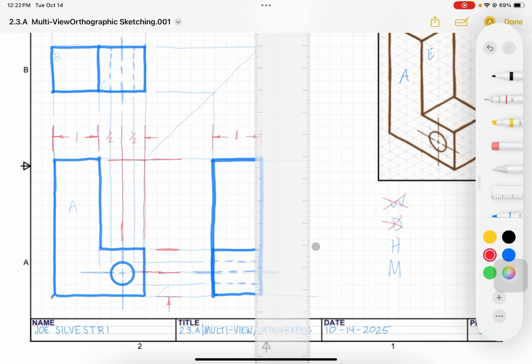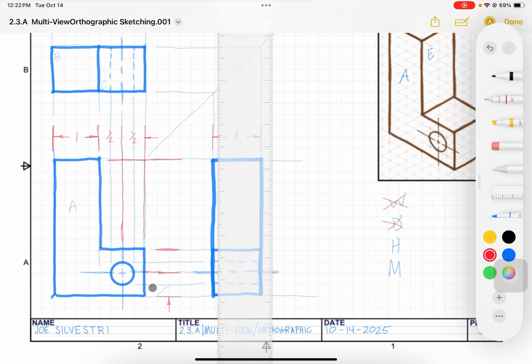So I want to go 2 blocks, right? So 2 blocks. So I've got my 1 block gap, 2 blocks for my dimension line, then the extension line extends 1 block past. So I need, let's see, I got this arrowhead on the outside here. I can't put it on the outside on this side because it gets in the way of this dimension, but I can put it over here. Okay, so that means this arrow is going to work for this measurement, and this measurement. Okay, so let me put the other one in here.